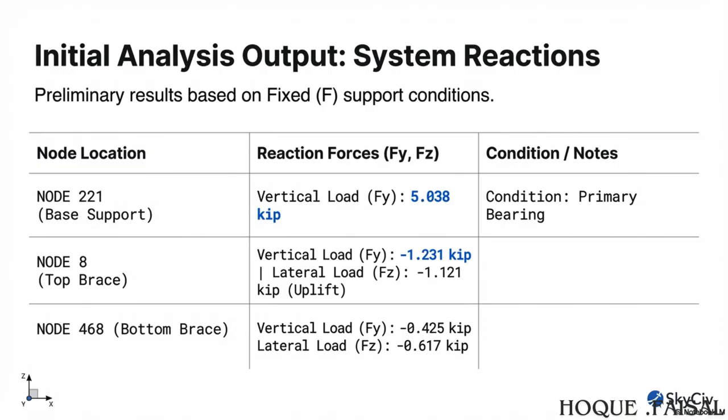So let's try to synthesize all this. We started with a report that looked absolutely perfect. A-plus work, send it to the client. And we discovered it was actually a very detailed, very precise map of a place that doesn't exist in the real world. We learned about the concept of fixity, the difference between holding a broomstick with your fingertips versus burying it in 2 feet of concrete. And we learned how confusing the code FFFFFF for concrete and RRRR for fingertips can be when you're staring at a complex 3D coordinate system.